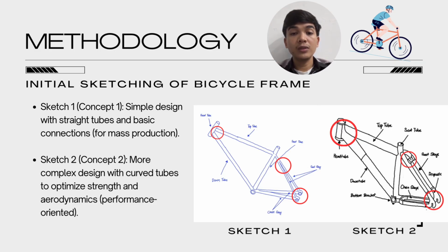However, because of its simple shape, this design may not discharge stress efficiently, which can make it more vulnerable to cracks at the joint under repeated load. Still, it remains a practical choice for low-cost everyday bicycles where manufacturing cost is the main priority.